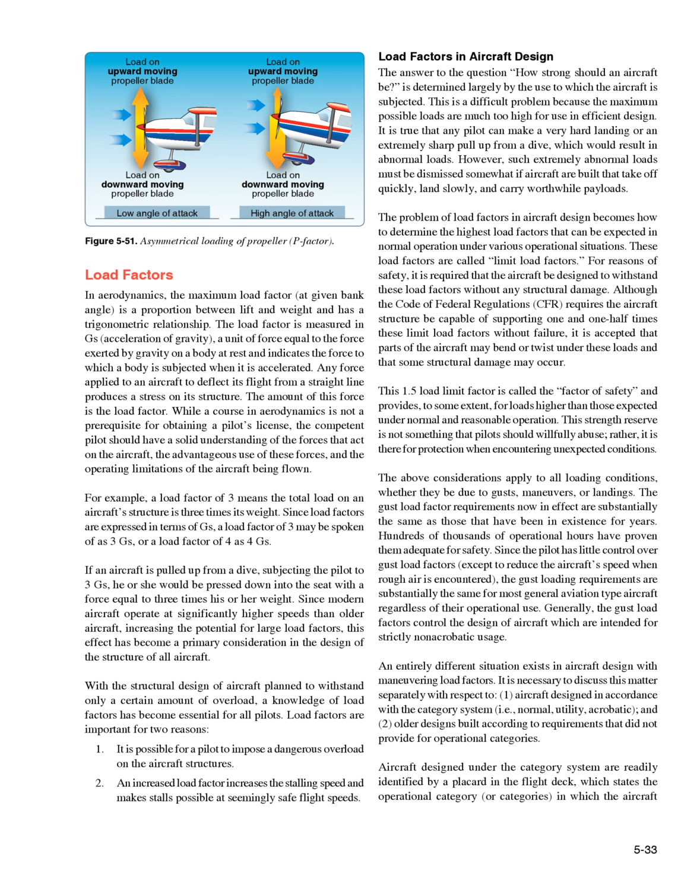Load factors in aircraft design. The answer to the question how strong should an aircraft be is determined largely by the use to which the aircraft is subjected. This is a difficult problem because the problem of load factors in aircraft design becomes how to determine the highest load factors that can be expected in normal operation under various operational situations. These load factors are called limit load factors.